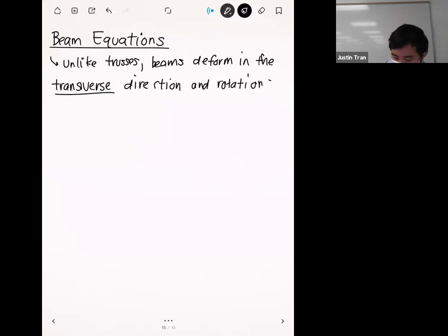If you recall, before we did ANSYS activity 4, we discussed how the thing that's unique about shell and beam elements is that they can include rotations as well. And that's what you mainly see here. Visually, it looks like this. Here is our beam, and visually it looks the same as a truss element.